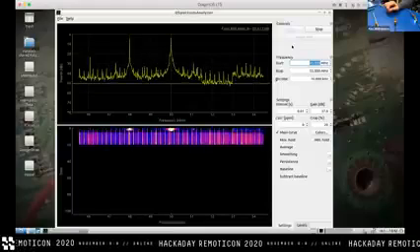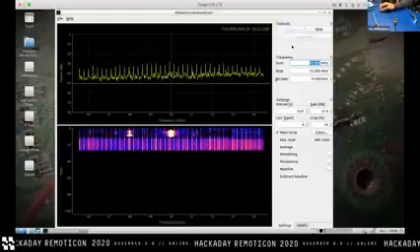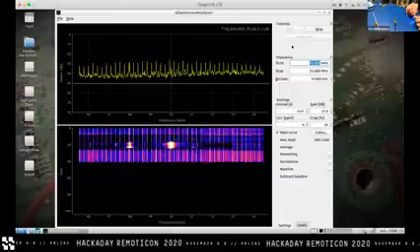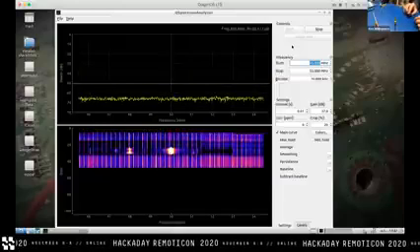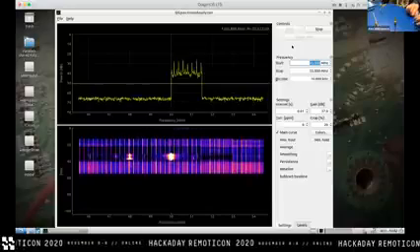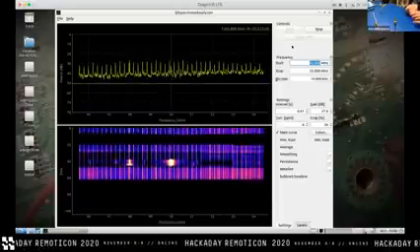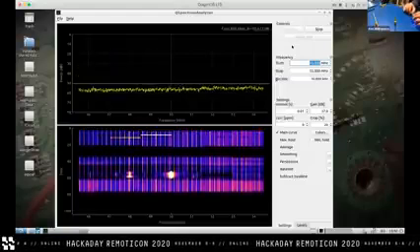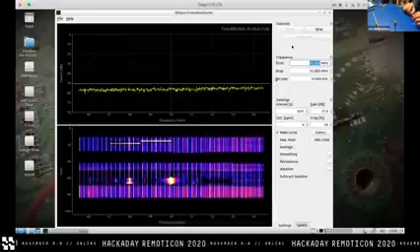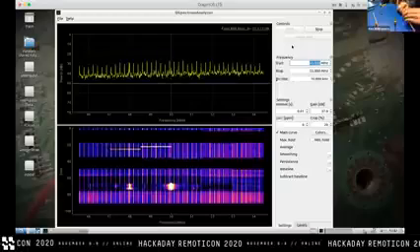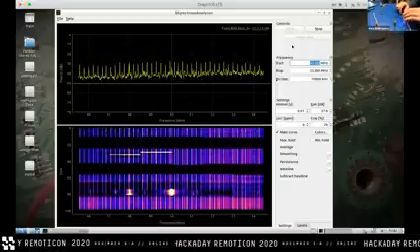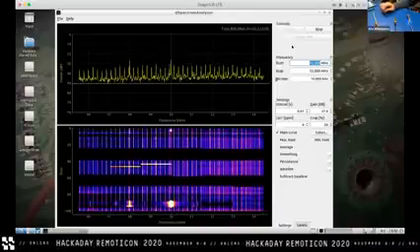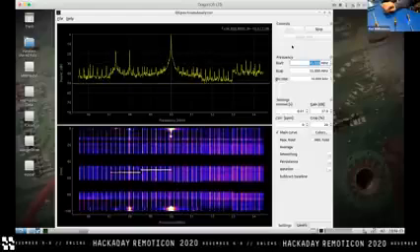If we take our probe and wave it over, this is another one of those situations where we've got a lot of peaks going on here, and if I simply unplug the LNA, that's interesting. All of those disappear and the noise floor drops precipitously. So we are actually measuring either RF interference that's going on in the room right now, which is entirely plausible, or, yeah, I think we're actually measuring real RF, because if I unplug our antenna completely from the low noise amplifier, the noise floor drops as well as all of those individual spikes. So what we're seeing on the spectrogram here is real. Who knows where it's coming from? I'm not going to try to find out for now.